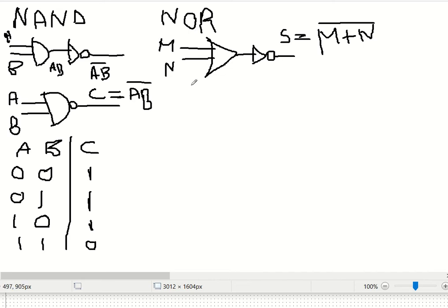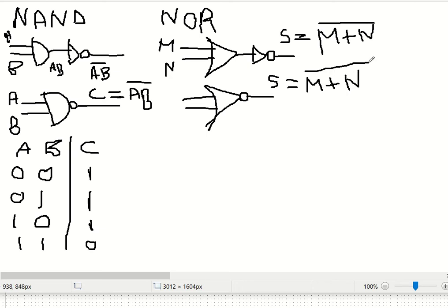So you can again simplify it using one specific NOR gate IC, which is 7402. Okay, 7402. So your expression would be similar: (M plus N) whole bar, and your inputs would be M, N. So this inverter is just converted into a bubble in front. Okay, that's it. So you can make your truth table as well.